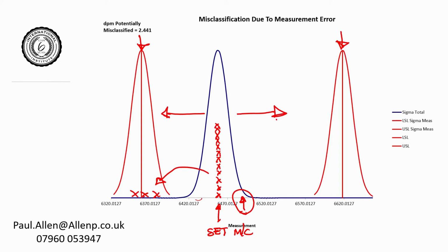So this is the difference between the two rules. Is my measurement system any good? Normally you would pass the two rules, precision to tolerance and precision to total. Both of them you want to be down at the 0.1 level. That would be the basic MSA rule. But in this case, this is perfectly capable of doing the practical job you asked it to do. So it's not passing the theoretical rules, but it's passing the practical rules.